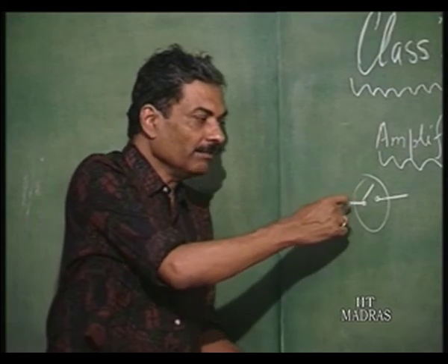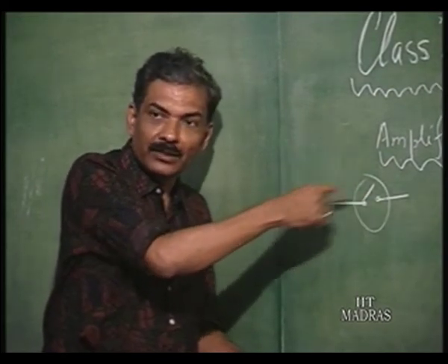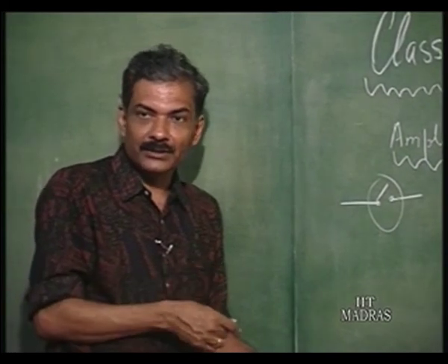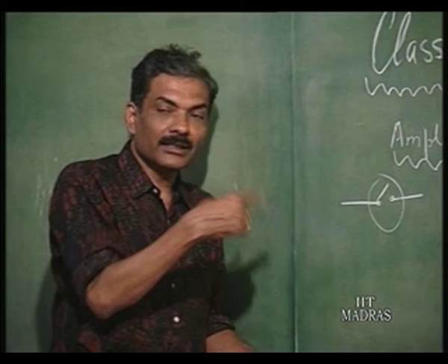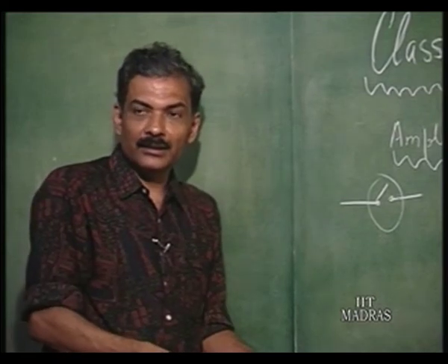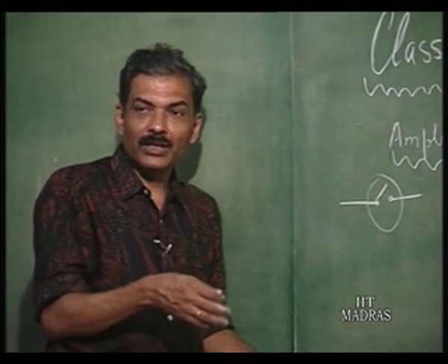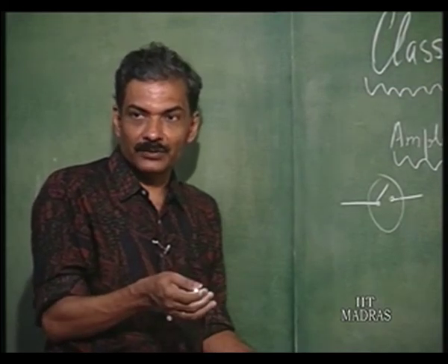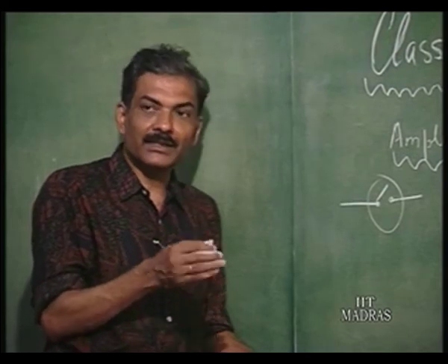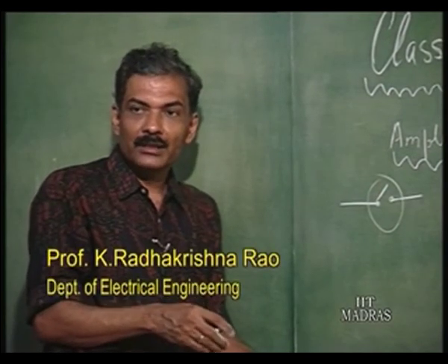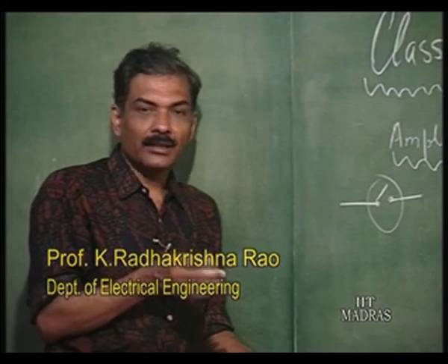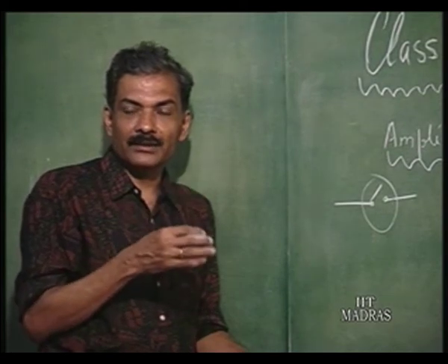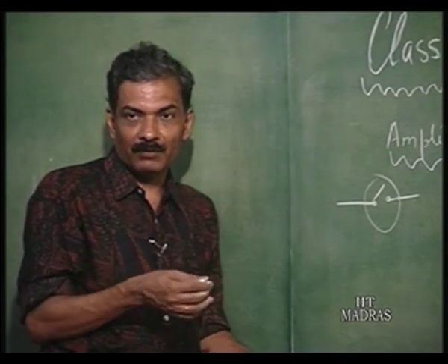There will be some current even when it is open, that is called leakage current, and some voltage even when it is closed, that is called saturation voltage. And apart from that, the circuits that will eliminate the harmonics will also have a certain amount of power loss. Such is the case with class C amplifier also. So, with the resultant effect efficiency will come down, and still it is going to be the most efficient power amplifier existing today for linear power amplification application.